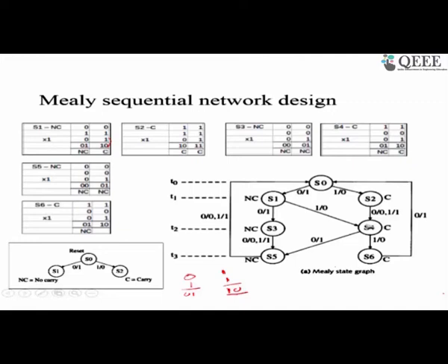See, why we can go to the same state is because all that we remember in S4 is that there is a carry bit which you have to make use of in the next bit processing, and 2 bits have been processed, 1 bit followed by another bit. That is why we use this one. We could not use S2 because S2 remembers 2 things. There is a carry bit and only 1 bit has been processed. This remembers that there is a carry and 2 bits have been processed.